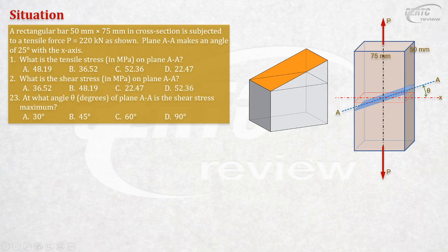This is very easy. There is a formula for this. Alright, so we want to know the stress along this plane, AA. The dimension of the plane is A. Okay, let's derive. Let's say this is A, this is B, and this angle here is theta. Of course, this is also A. So, this is a right triangle here. This is B. So, the length of this inclined area will be B over cosine theta, because cosine of theta is B over that hypotenuse. So, this length is B divided by cosine theta. Alright? So, this is our P.